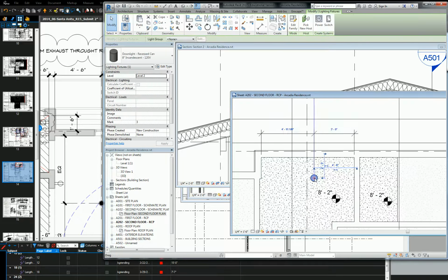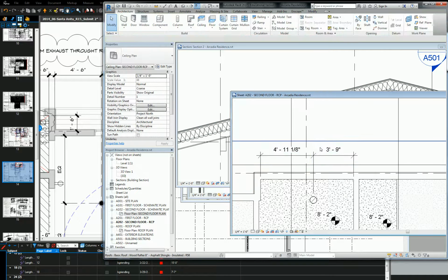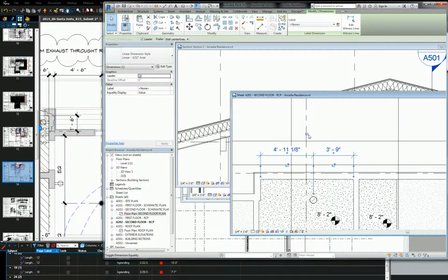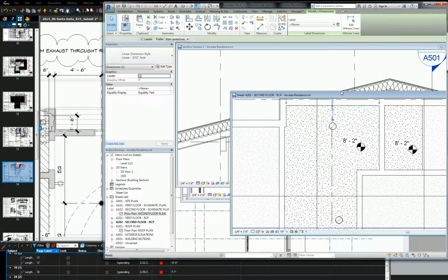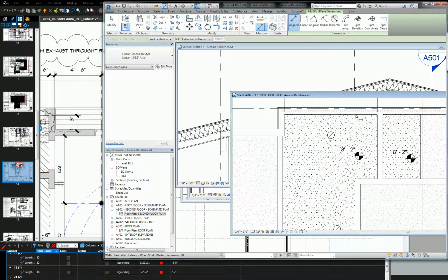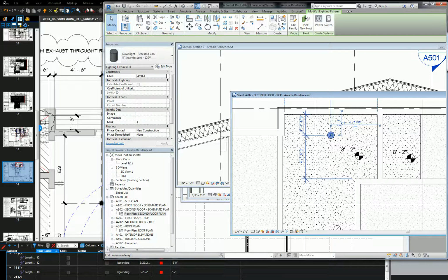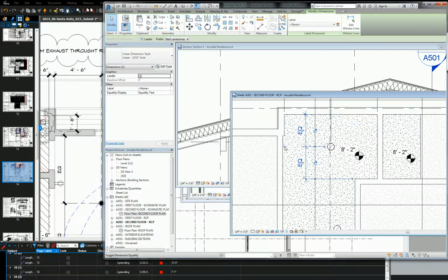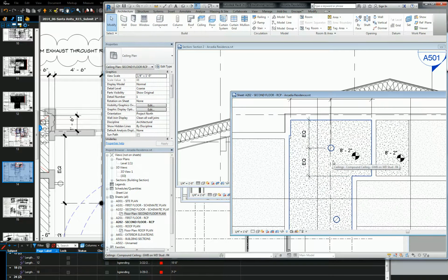You dimension the center line of the object to two reference points, and then you select the dimension, and you click this little EQ with the slash in it, and it toggles it to be equal in the space. It's genius. It's awesome. In fact, I want to do a video on just that, because it's super awesome. So select the dimension, equal, so that's where that light goes.